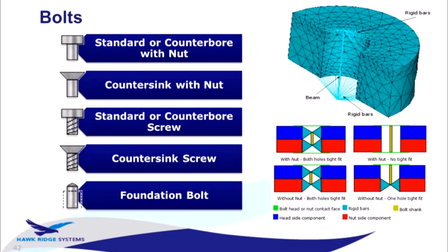Doing this manually is incredibly tedious. If you were to go back 10 years and use a different analysis tool, it is incredibly painful to build these elements. And the good thing about SOLIDWORKS is it interrogates your model and basically says, hey, I know the size of this hole. I'm going to construct this geometry automatically. I'm going to tie it to the faces you told me to tie it to and just go forward with it. You don't need to understand the underlying analysis technique there. It'll go off and report the axial load, the bending moment, and the shear force exerted on that bolt.